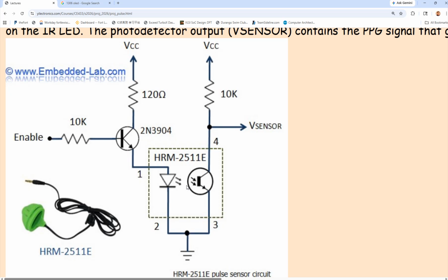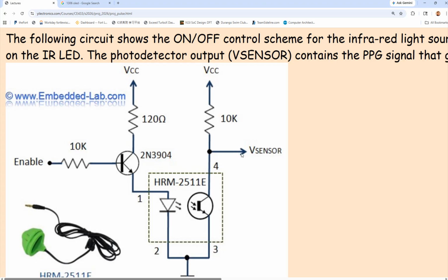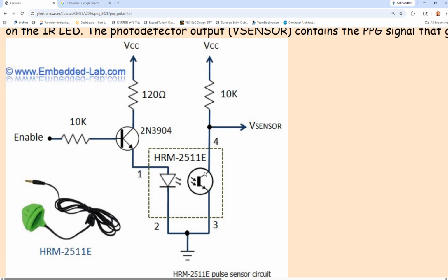If there is something being received at a certain level, that means you are getting current to the ground, right? So this voltage wouldn't be what? Exactly. It wouldn't be VCC all the time, because this is not always blocked. If this is blocked, this is off, then this is pulled up to VCC. However, your finger is not totally blocking the IR light, so it's not always off here. So it's on a little bit, so you always have current flowing through it.